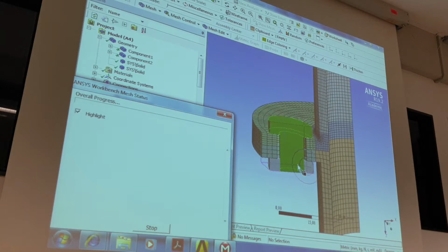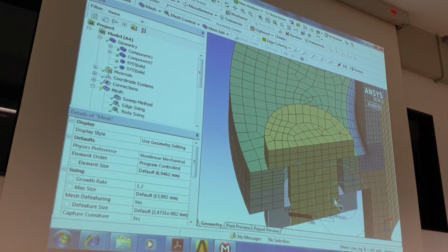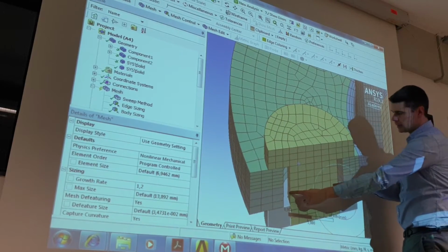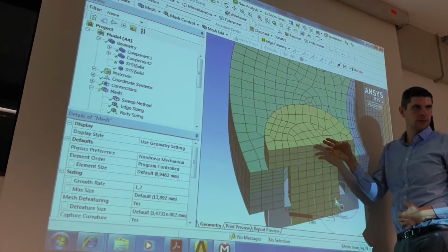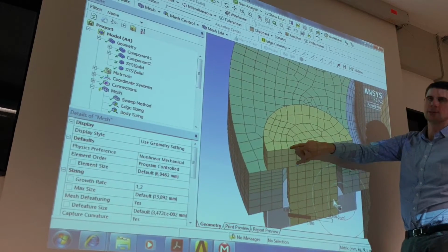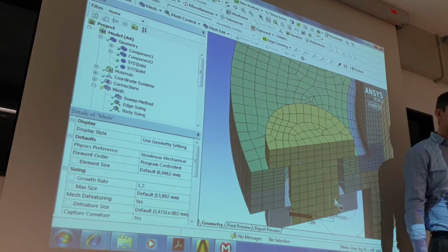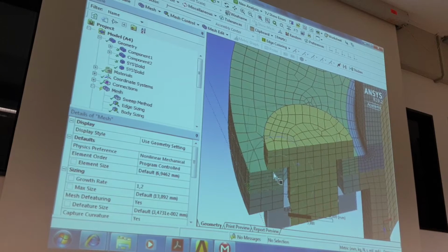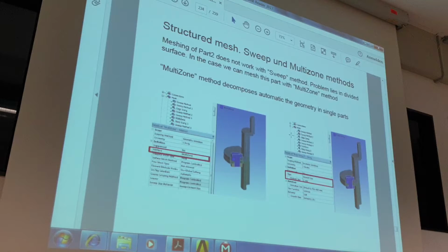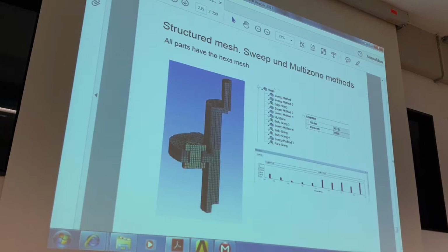We will see exactly it. Look, yes, if you show how your geometry looks like, you will see the program slice. Yes, like I told you, if you slice here, then you can sweep this body. You see here exactly radius, yes. So the program sliced this geometry automatically and then connected it. Yes. So, and the last part, like in lectures, is okay, 2 millimeter also.